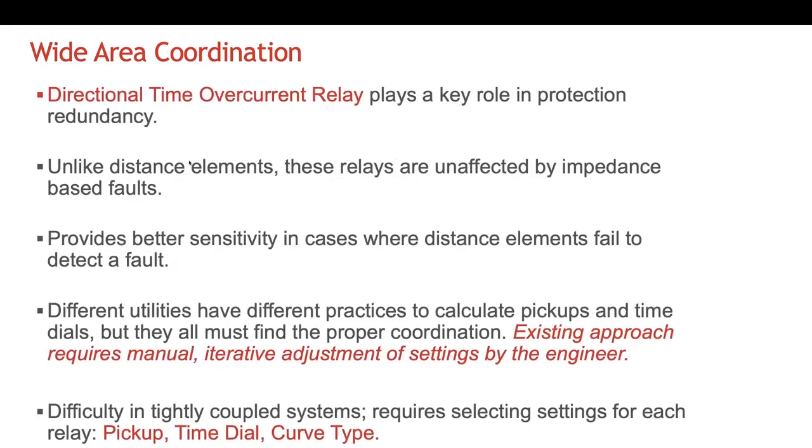So we chose to focus on directional time overcurrent relays first. They play a key role in system protection and the redundancy of the system. Unlike distance elements, they're not affected by impedance-based faults, and they do provide better sensitivity in some cases over distance elements. Different utilities have different approaches to calculating pickups and time dials, but they all have to find proper coordination in order to assure reliability of the system and avoid misoperations.